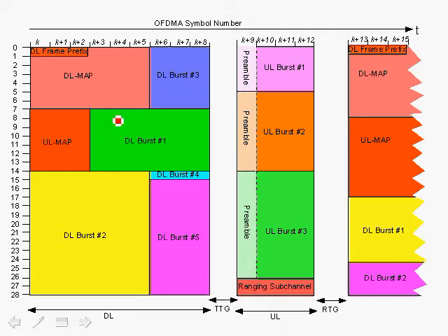Now the multiple access comes in the uplink in particular, where with one OFDM symbol we are actually sending data from 3 users who are simultaneously accessing the network and sending in parallel. All transmitters on these 3 subscribers are active in transmitting data. I'm going to describe that in the next slide in detail.